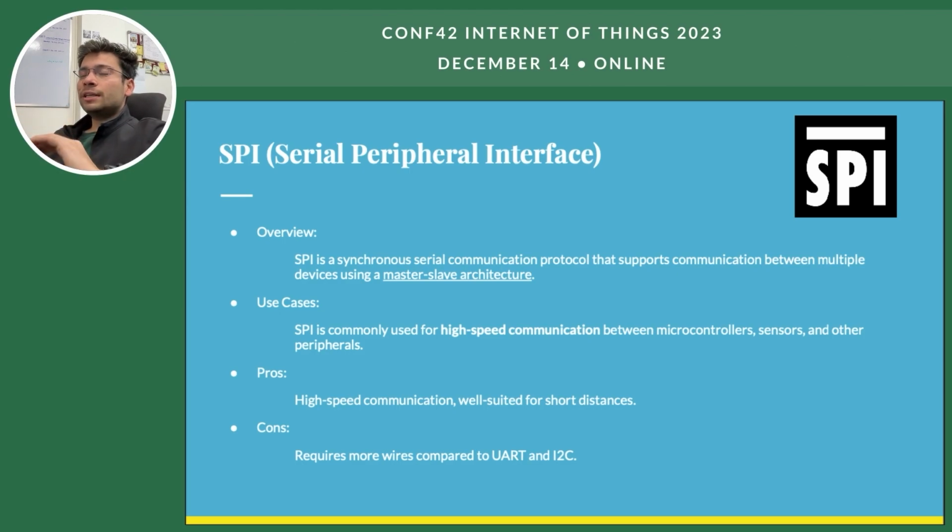The advantage of using SPI is it works on very high speed communication, but it requires more wires. It requires four wires to work for each slave. So if there are multiple slaves and one master microcontroller, then the number of wires will increase for SPI.